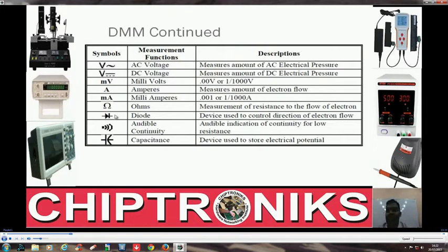This is a very important utility present in a digital multimeter, and people are very much confused about when to use diode range and when to use continuity range. So I would also discuss that point, when to use diode range and when to use continuity. Continuity is a simple procedure to measure the continuity between the circuits, or to measure the low resistance.